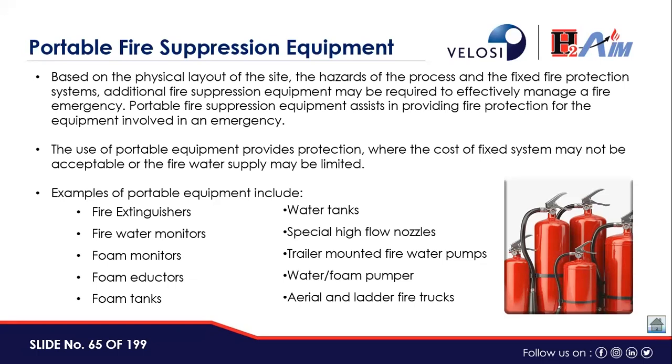Only cooling is effective, and other parts mostly depend on the relief system in LPG, because LPG, if repressurized, will release to flare. And from a firefighting concept point of view, on the piping system a combination of Deluge system, spray system, and some foam can also help. Okay.